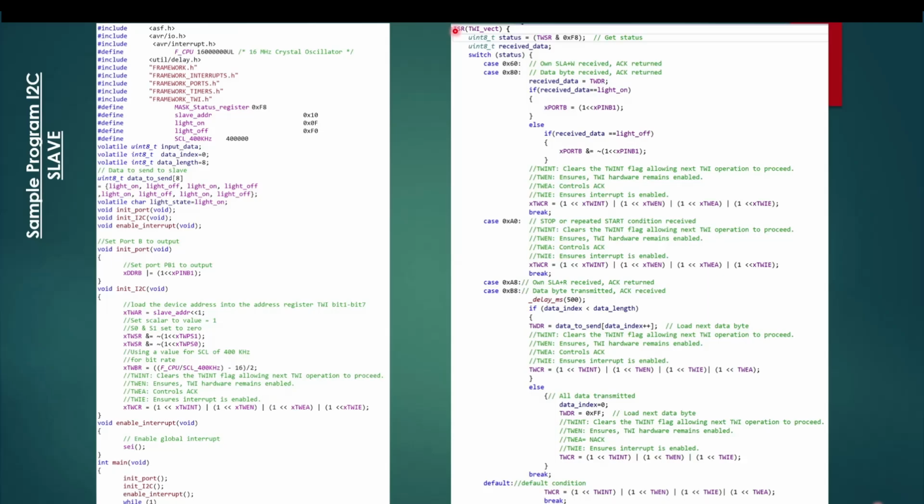So in our case, what we expect is that the first interrupt is going to be hex 60, which means that the slave got for his own address a write command. So the next time it's going to get an 80, it has to be ready for receiving data. So the next interrupt, if there is new data, it gets a code 80.